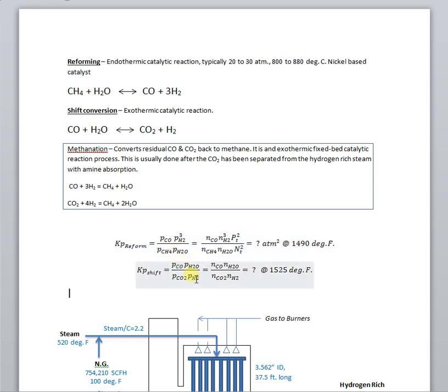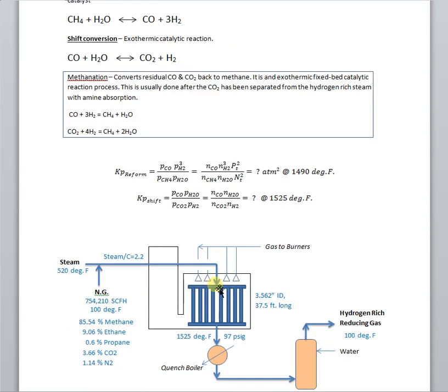Since the reformer is a continuous flowing process of limited size and residence time, equilibrium between these reactions is not completely obtained. So in sizing the furnace, a specified approach to equilibrium will be required. In the following example, we will assume a 35-degree approach. Here is an example.